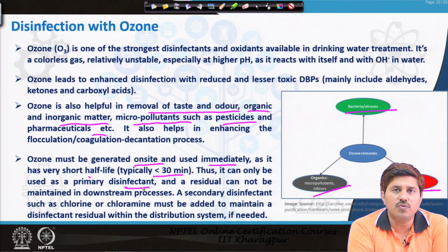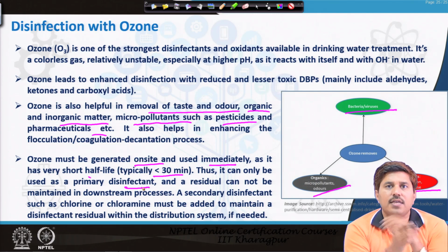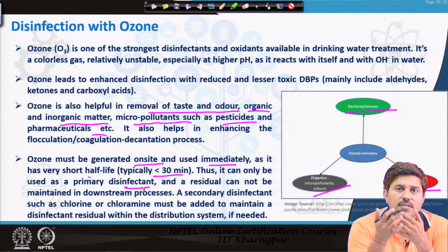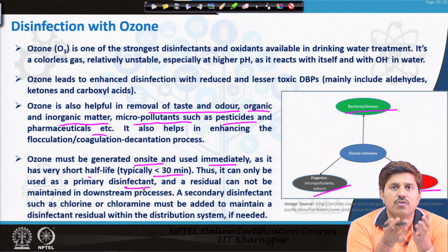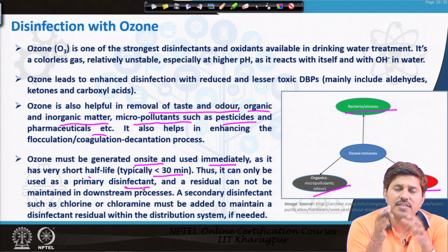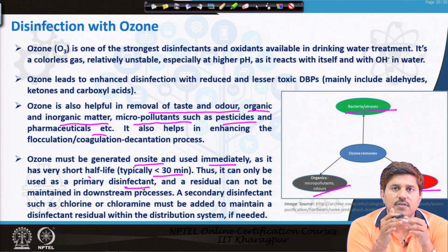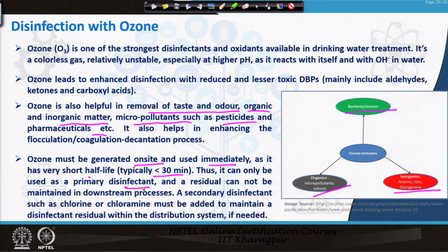That is one of the unique advantages of chlorine systems, that they leave a residual in the system which ensures future safety as well, whereas ozone, or for that matter UV or ultrasonic ways of disinfection, will disinfect very effectively, but the disinfection lasts only while they are in contact. After that, the potential of regrowth is very little or almost negligible, but recontamination may occur, and if recontamination occurs, it is not going to help in any way.